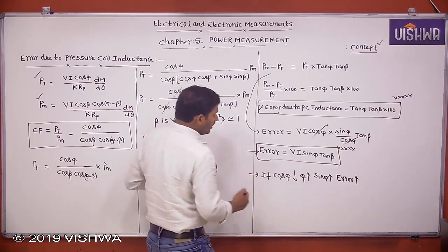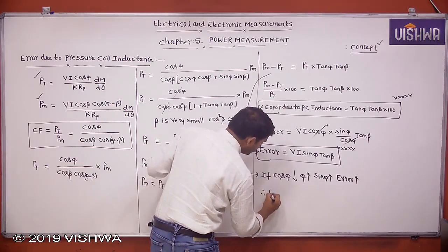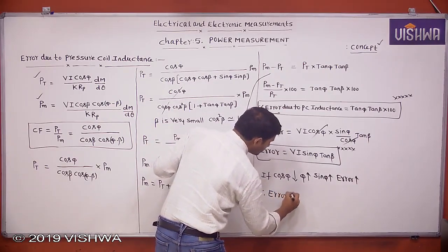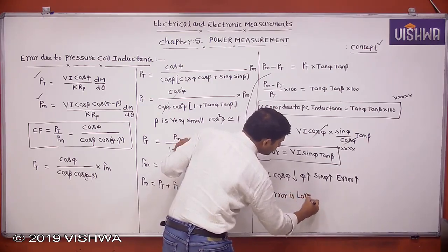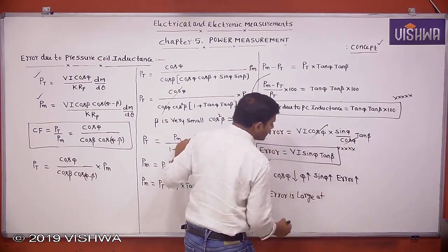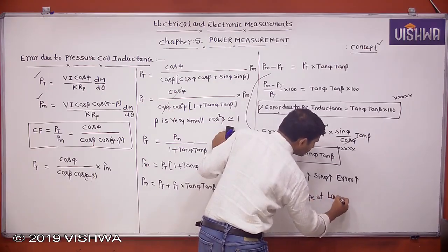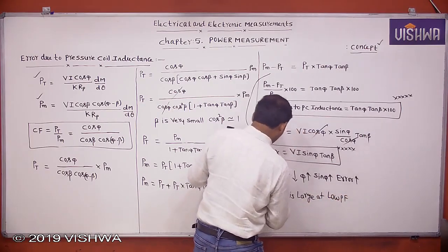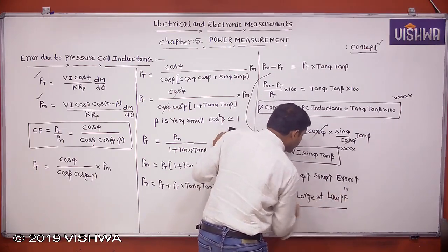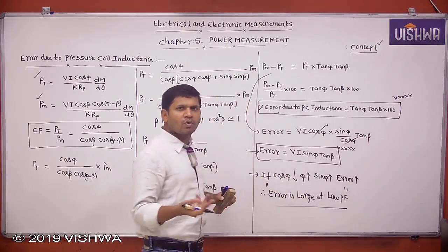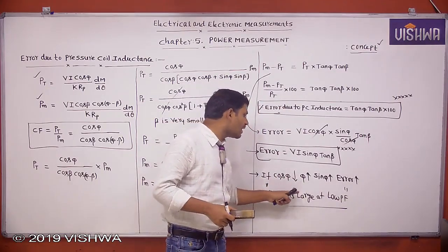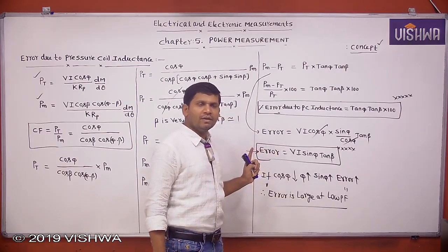Therefore, error is large at low power factor, whether lagging or leading. That is the point to remember.